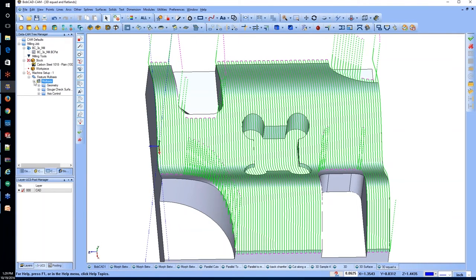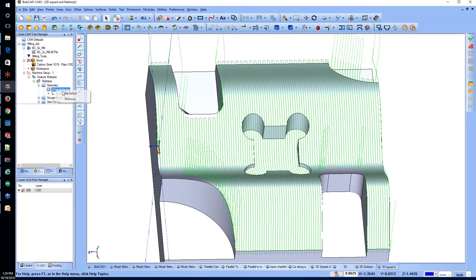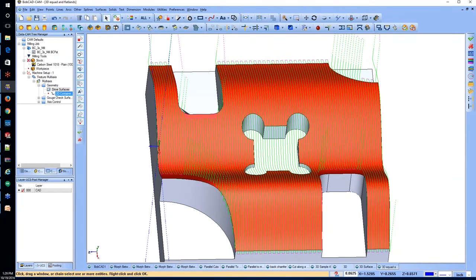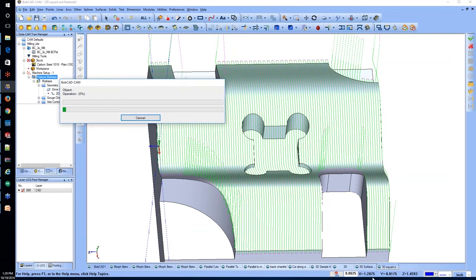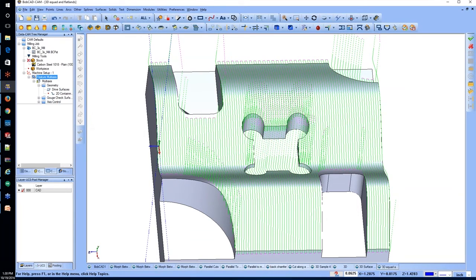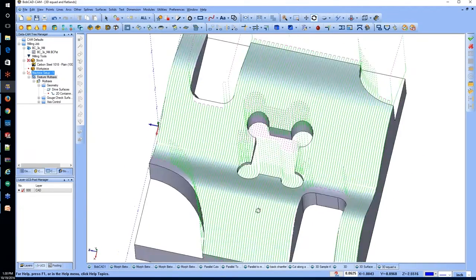And all I have to do is go in here to the geometry, select it, recompute, and update it. So you guys can file merge. What I'll do too sometimes is put one of the files on a layer down here. That way, if I need to modify anything, because I'm only changing maybe one or two toolpaths depending on the change, why change all of them? I'd have to restart and do all that stuff. You can just file merge and select it anew.